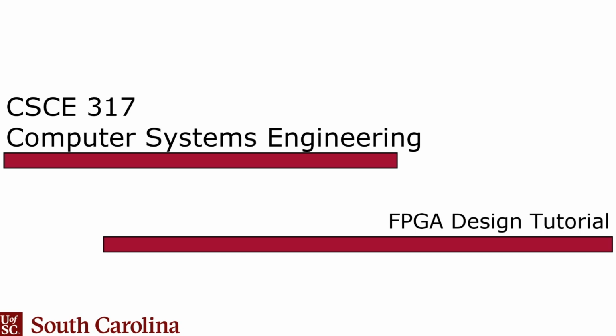The Arduinos are kind of flimsy, they're tiny, and the thing I don't like about them is that they have very limited debugging capability. You can't do line by line step debugging on them. I mean, well, technically you can, but the ones we had couldn't do it. It turns out, just so you know, in case any of you use an Arduino, the Arduino has a reset pin on it. And on a typical Arduino, and when I say Arduino chip, I'm talking about the classic Arduino chip, which is the Atmel 328P.